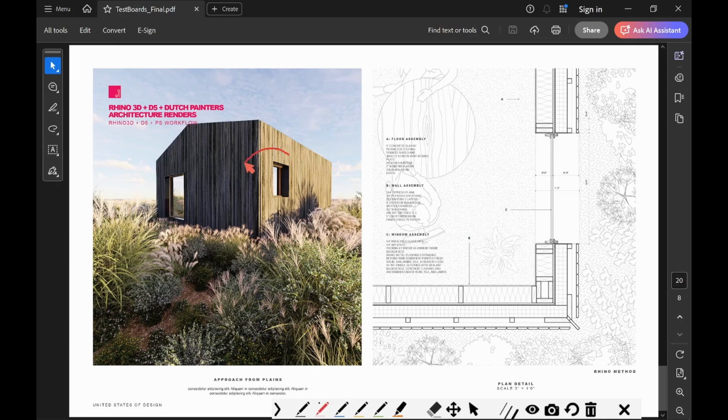So we're basically looking at this corner condition, right? And what's happening here is you have this wood slat facade, right? You have the wood slat facade here, okay? That's the first thing. And then you're going to have a little horizontal batten, and I'll go to the 3D model, but I just want you to relate it to the image. You're going to have the horizontal batten with the vertical batten. So that's basically your vented rain screen. That's where you can allow air to circulate through there.